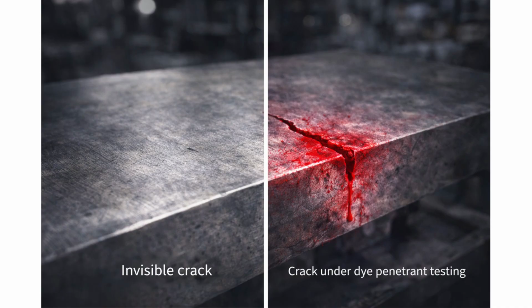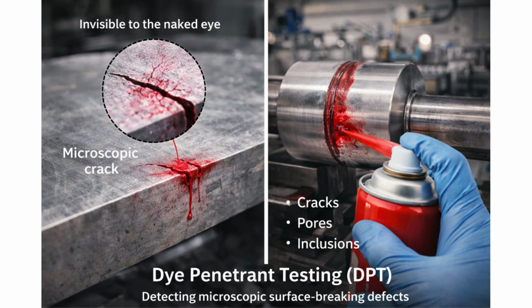They're so tiny that they're completely invisible to the human eye, yet they're large enough to cause catastrophic failures under stress. DPT is used in production processes to verify that materials and components meet specified quality standards during manufacturing, detecting surface breaking defects such as cracks, pores, and inclusions to ensure the integrity of the final product.